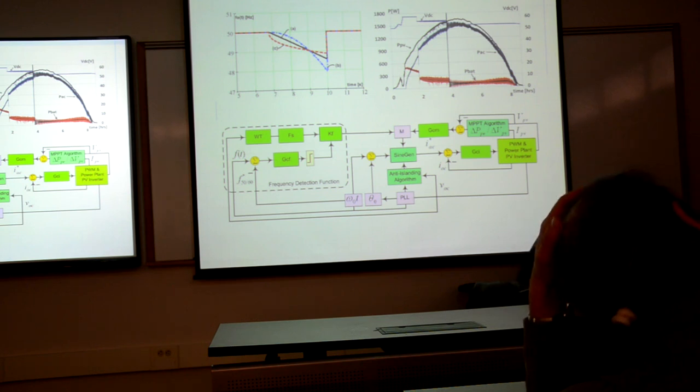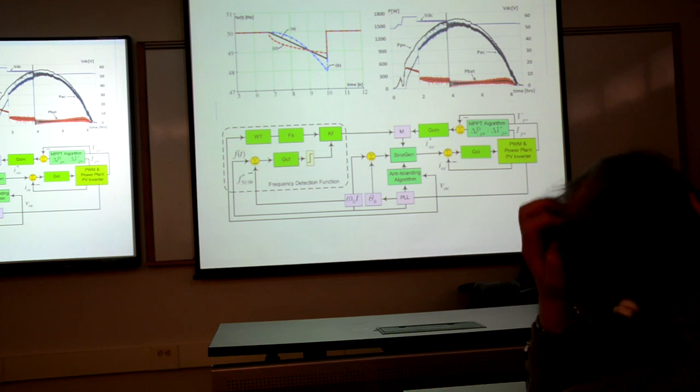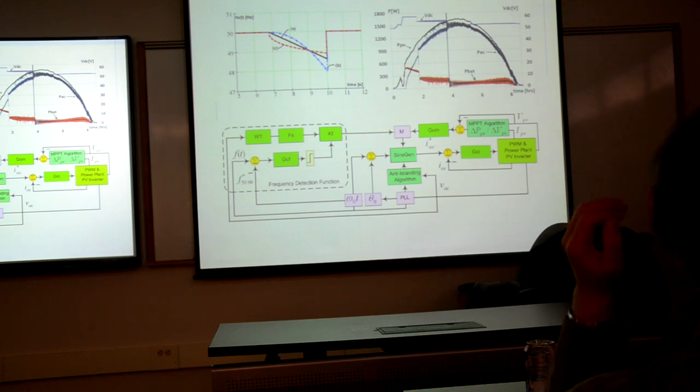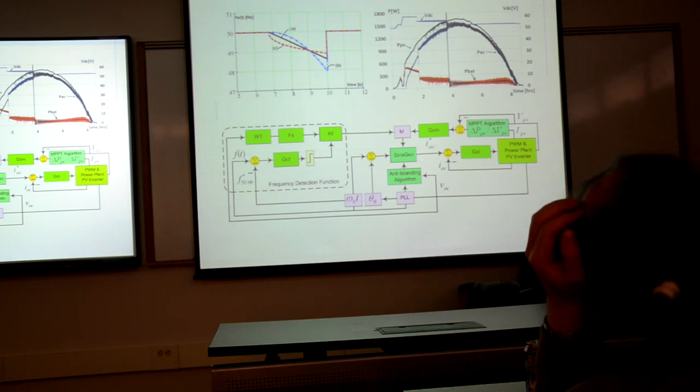If something happens or you decide not to operate with the grid, you can move to the standalone or islanding mode. The other thing, you need to control how you disconnect and connect to the grid, because you may have issues in terms of stability of the system. So that is the anti-islanding mode and the control of the system.